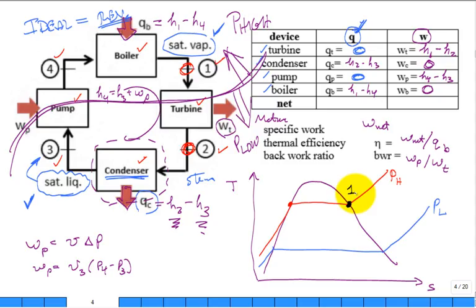All right, let's pick it up here. We've done second law analysis and first law analysis of turbines. True? If you have a reversible process, no entropy generated in the turbine, and we said the turbine's insulated, so the Q of the turbine is 0, what do we know about one of the properties? One of those properties that you know from thermodynamics is constant through the turbine. What is that property? Enthalpy? Is the inlet enthalpy equal to the exit enthalpy of the turbine?